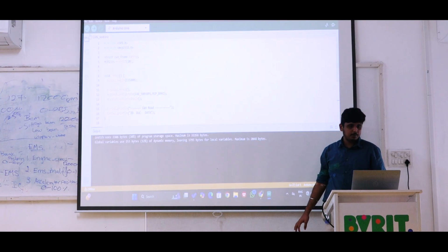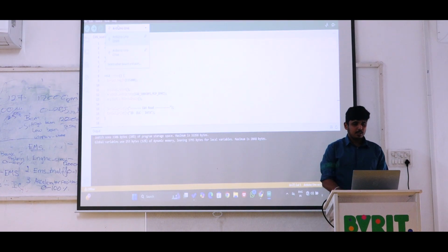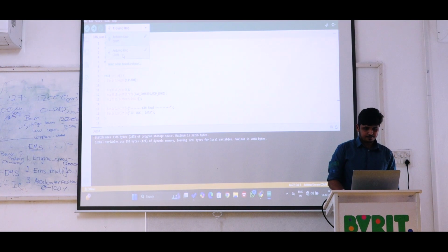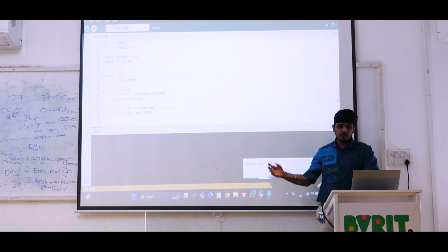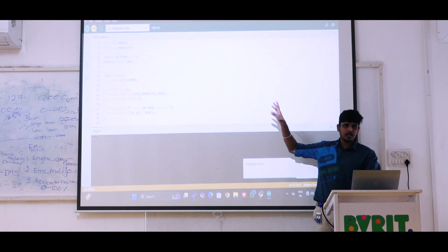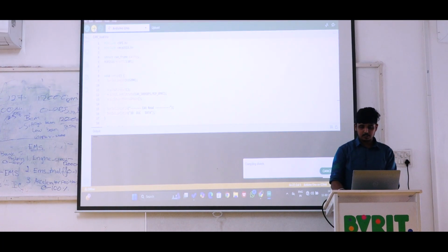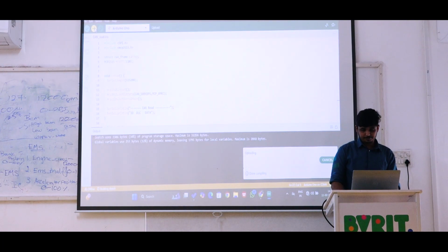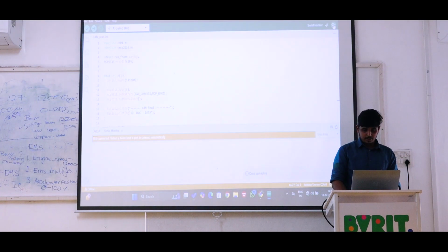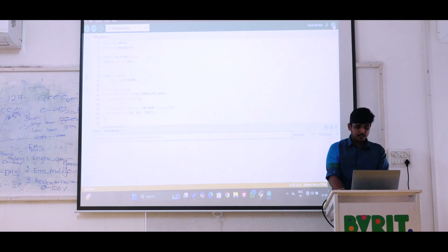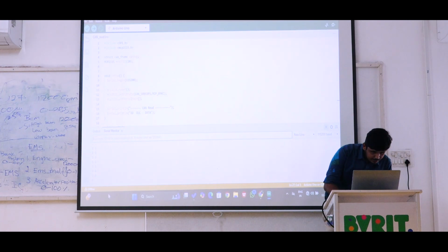After that I am going to upload this. Further I am going to set up the port. Before uploading you just check if the port and boards are correct or not. Here it is uploaded, and see it is getting 0, 0.